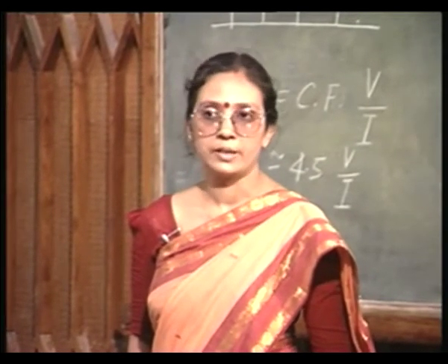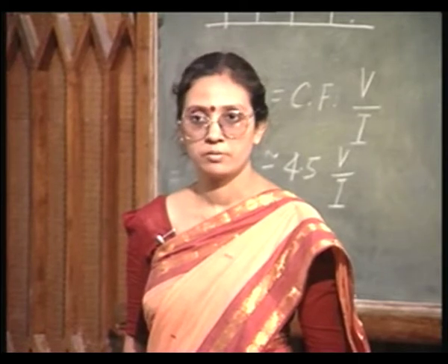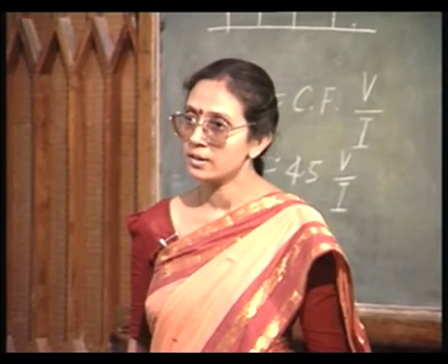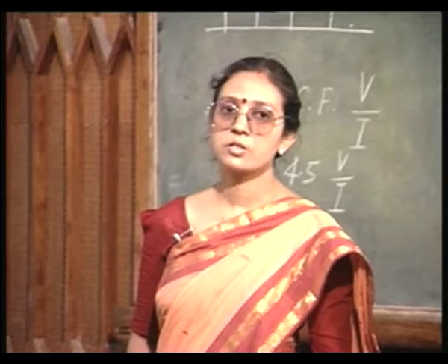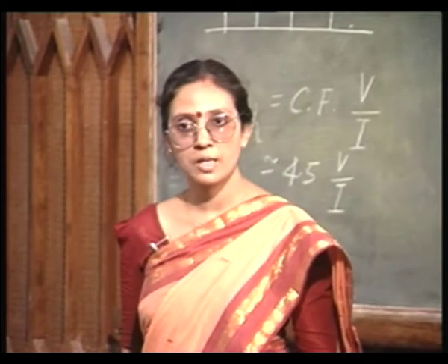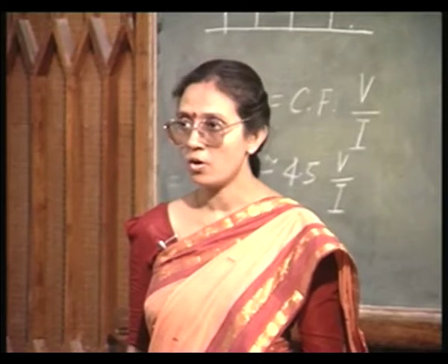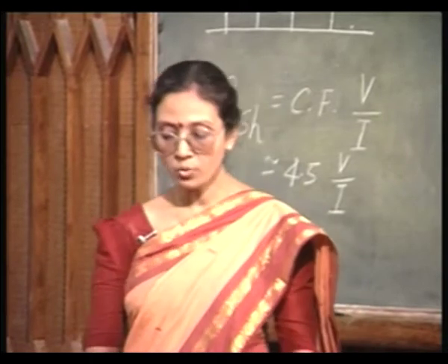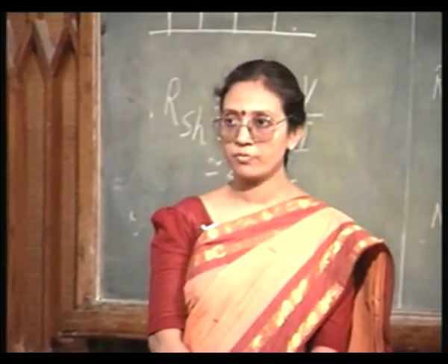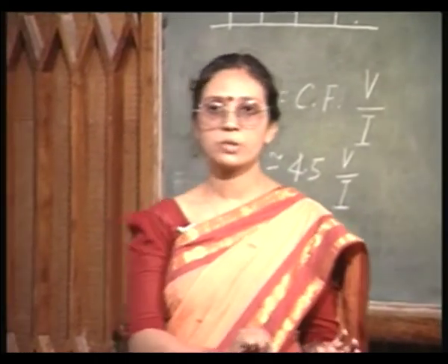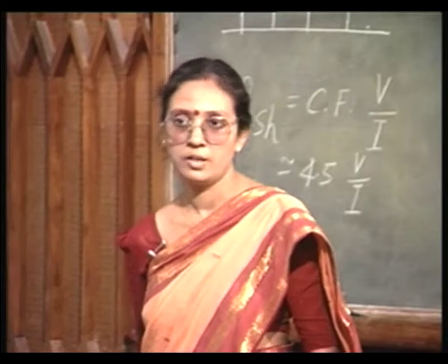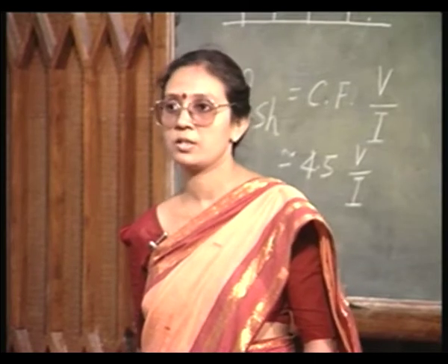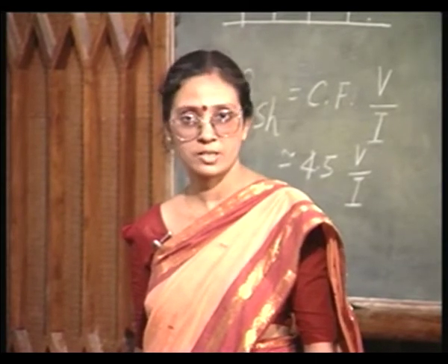There is one very simple technique, by anodic oxidation. What you do is you just anodically oxidize the semiconductor. Since in anodic oxidation the oxide thickness is proportional to the applied voltage, you know exactly how much oxide you have grown, and that is exactly how much silicon you have consumed. Okay. Now, you first measure the sheet resistance on the surface, then you grow a thin layer of oxide, and etch that thin layer of oxide, okay. Again measure the sheet resistance on the newly exposed surface.